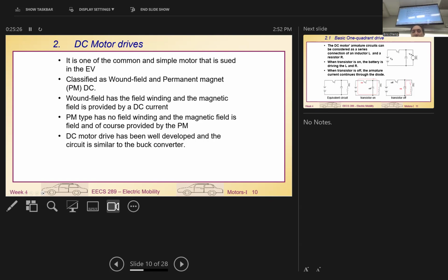Now let's discuss briefly the DC motor system. We use the DC motor because it's one of the really common motor drive systems. I think some of you may have learned about them in undergraduate. Here, basically, we have two major types of DC motor. One is called a permanent magnet DC motor, PM, and another is the wound field. With the wound field, we don't use PM to generate the magnetic field; we use a winding. The winding generates the field by itself, so you need an additional field winding. The field winding can be excited by a separate voltage source, or excited together with the armature current.